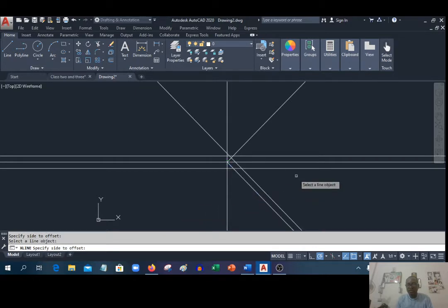If I click this and move sideways, you see, now you're seeing it as a continuous line. Because I trimmed it and we're using construction line now, that's why it's taking it from infinity to infinity, right? Now let me also explain. There is actually a tool in the modifying tool called offset, right? For these shorter lines, let me erase this tool that is long and use this opportunity to explain that tool offset.